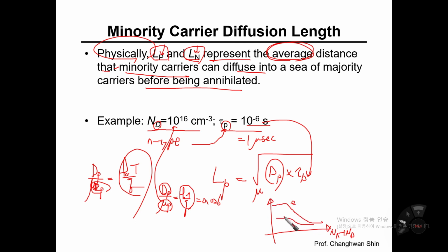That is for electron, that is for hole. So once you know the total concentration of impurities, in this case Na is not mentioned, so say Na is 0, then 10 to the 16 here, and now we are talking about the hole, so read out the value, maybe 400-ish.